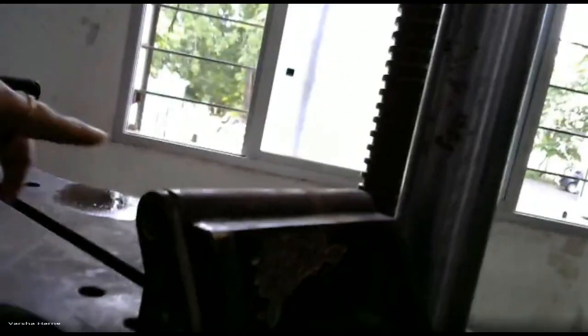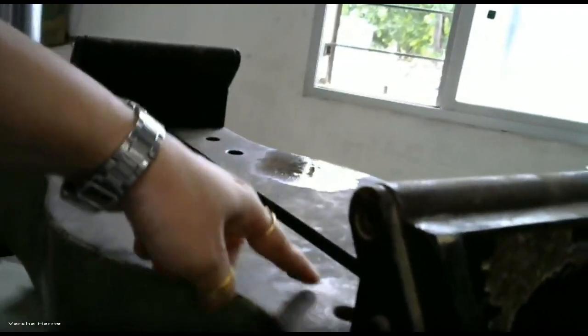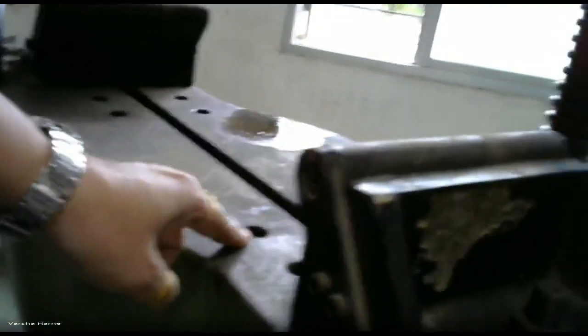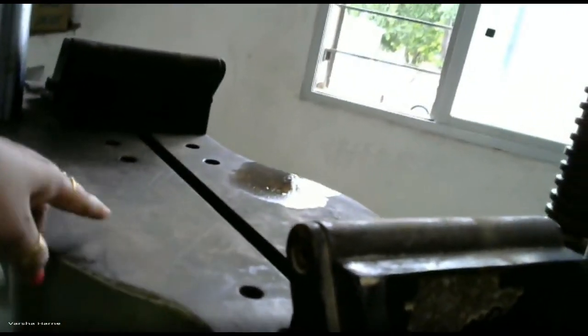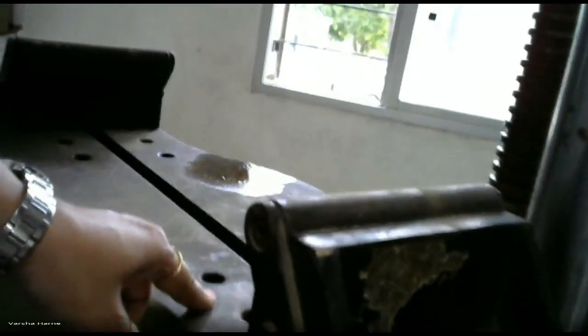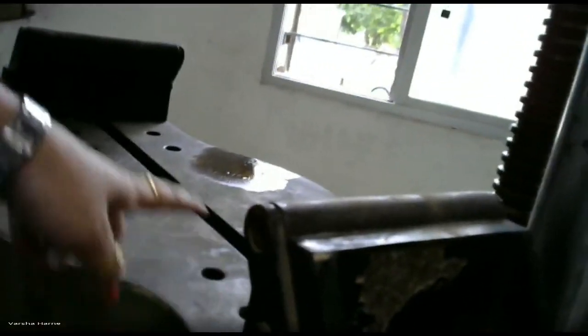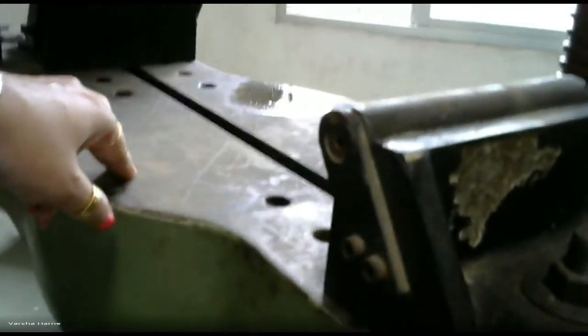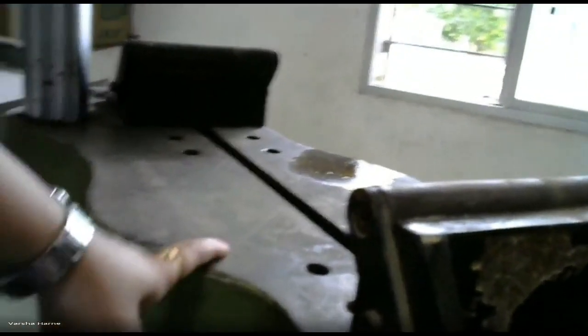Now see here, during the bending test, there are two supports, one is called our fixed support and the other our simple support. That's why we perform the bending test here. There are different holes at pitch distances, and according to them the length of our beam can be changed. For example, if you perform the test on a beam length of 100 centimeters, 80 centimeters or 60 centimeters, the position of the supports will also change. So here we perform our bending test and here we perform our tension test.